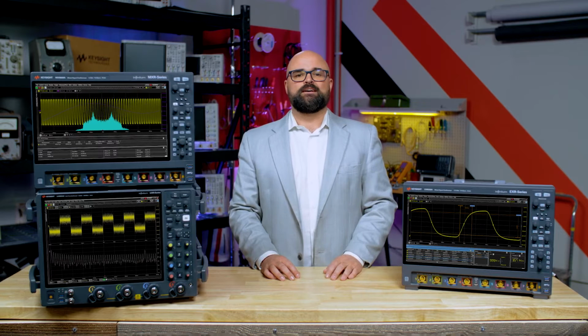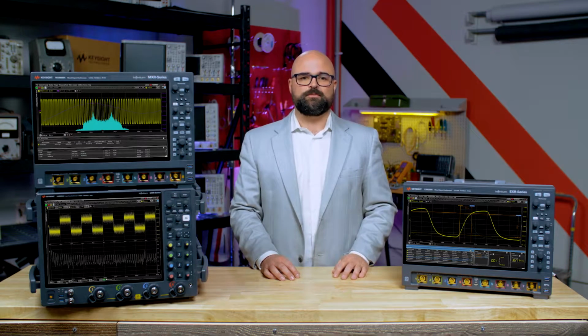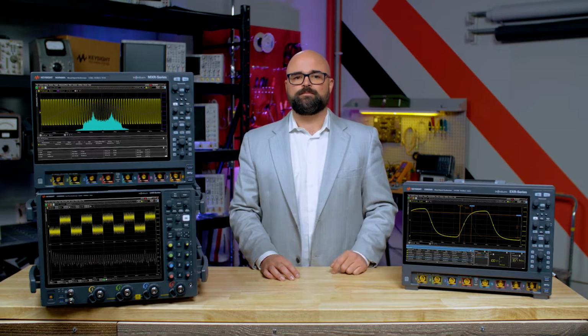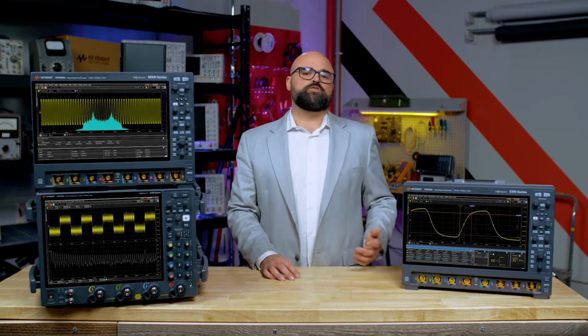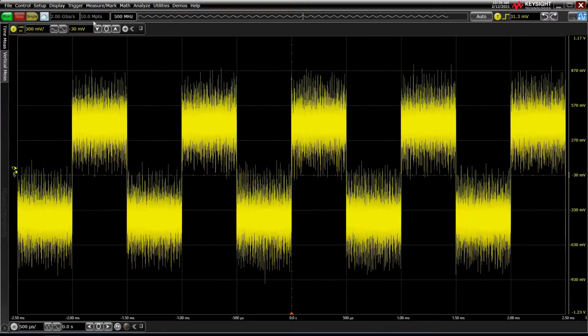Let's take a look at the capabilities and benefits of the fast Fourier transform, or FFT, a standard feature on our next generation Infiniium EXR, MXR, and UXR series oscilloscopes. To learn what an FFT is and does, check out the Scopes University class linked in the description. FFTs let you quickly and easily view the frequency contents of your signal. With Infiniium, they're a special type of math function and can be turned on under Math, New FFT.